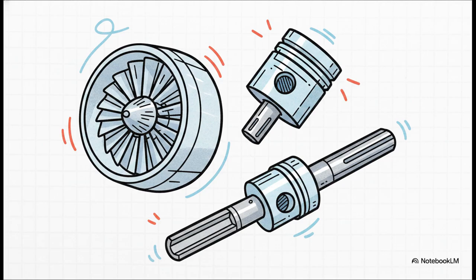Think about a precision spindle or a massive turbine shaft inside industrial rotating machinery. At those extreme high RPMs, even a microscopic uniform surface deviation, or just a tiny bit of taper, can cause catastrophic vibration, tear apart a bearing, or blow a seal. In those cases, total runout is basically your engineering insurance policy. It guarantees those parts spin smoothly and seal perfectly.